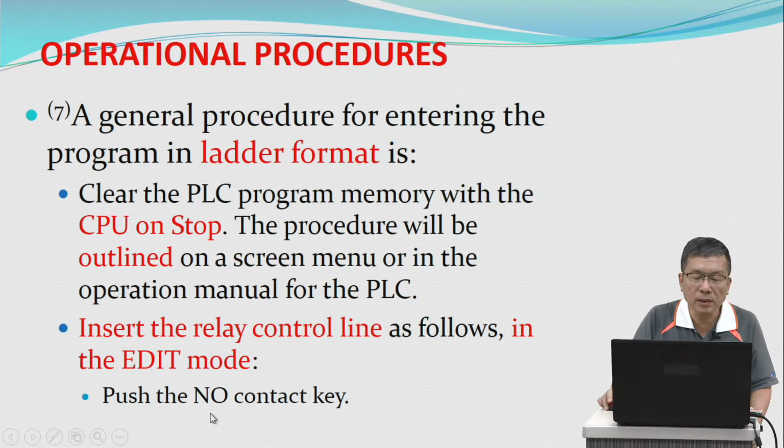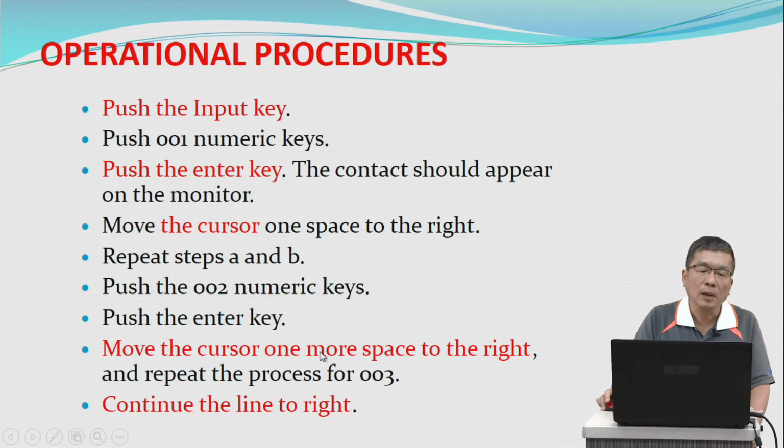Push the numeric open contact key. Push the input key. Push 001 numerical keys. Push the enter key. The contact should appear on the monitor. And then move the cursor one space to the right. Repeat steps A and B.